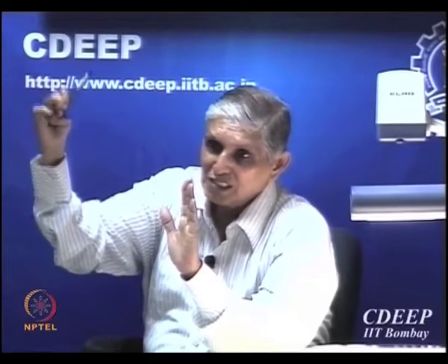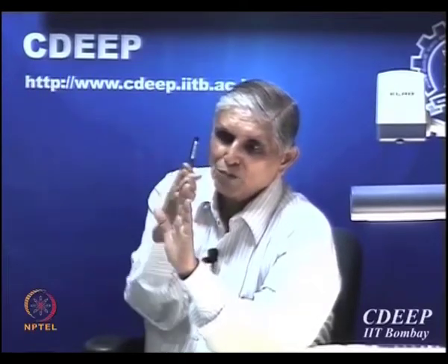So right at the start, C1 is giving you a high pass filter, is that correct? This has to be understood: up to a certain frequency it may not pass, but beyond that frequency it will pass, is that correct? That means below this particular frequency the gain may fall, the input may fall, or that is Vg will be very small or negligible. Beyond that only full Vg will be made available to you. This is the trick we want to utilize, okay.